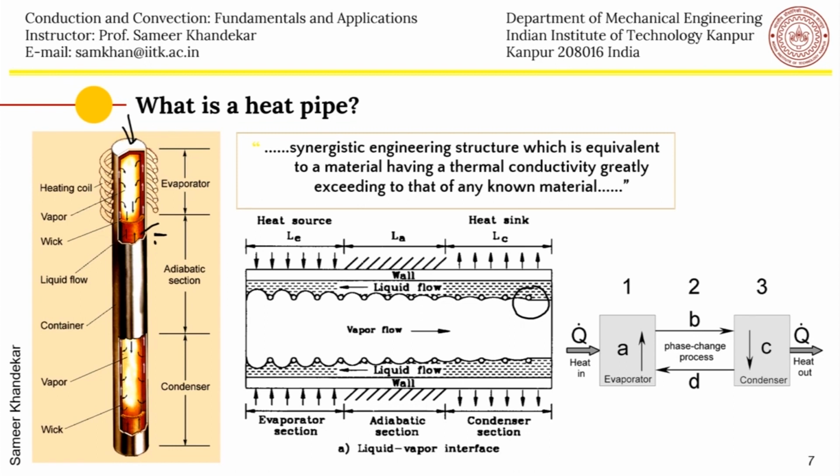The liquid will go and rest in the porous media, which is the wick structure, wrapped all around. So I can make a diagram here. You can see that the porous media in the cross section looks something like this. Because of the capillary action, the liquid will all go inside and rest, and the vapor will come in the vapor space in between, which is the annular space. This is the vapor space.